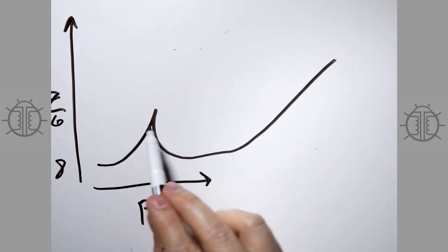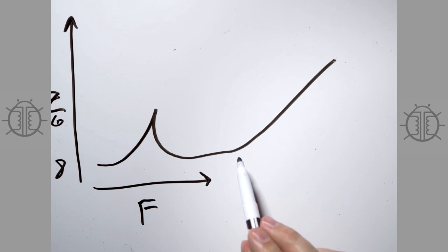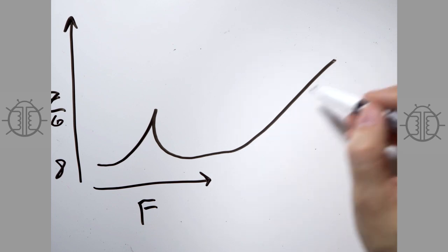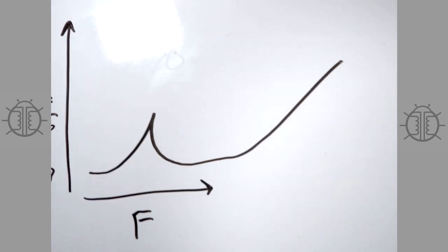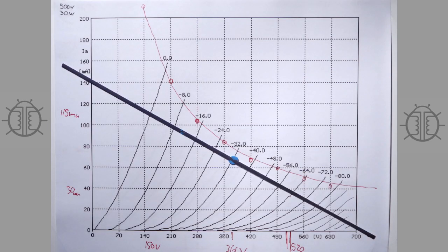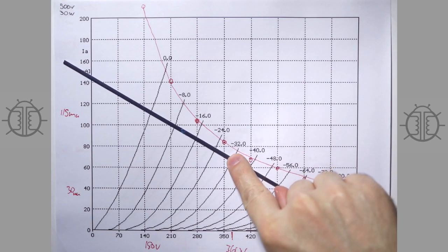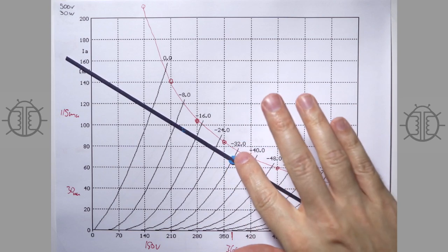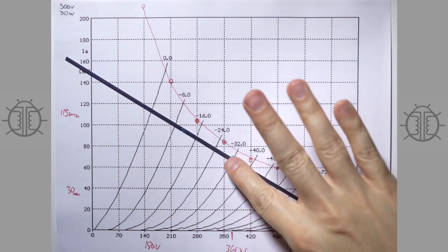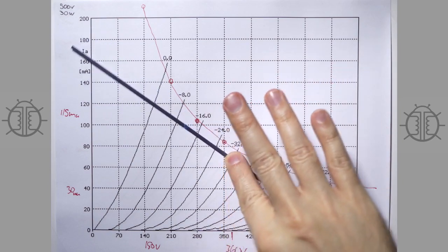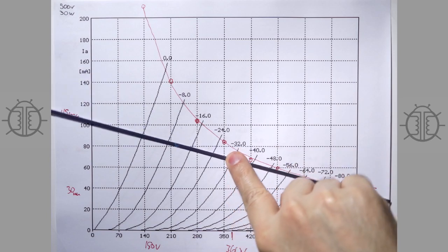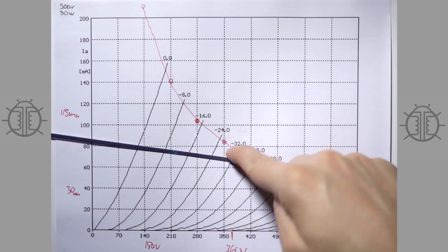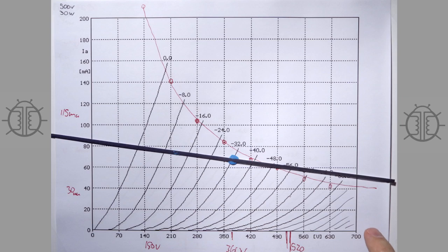And then it'll be 8 again for a lot of the operating point of the speaker, but then it'll go right up because the speaker becomes inductive, and it becomes a very high resistance load at higher frequencies. And so depending on the frequency you're putting into your amplifier and driving into your speaker, the load line does this. It might be like this most of the time, and then at speaker resonance, it kind of does this. You know, it straightens out, and you can see, whoa, now we're swinging up a lot more voltage,